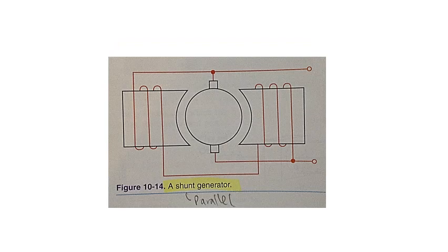The self-excited generator. A self-excited generator uses no separate source of voltage to excite the generator field winding. The self-excited generator produces a small voltage when the armature windings cut across a weak magnetic field. This weak magnetic field is caused by magnetism left over in the pole shoes or field coil cores after the voltage and current have ceased to flow. The magnetism left in a magnet after a magnetizing force has been removed is called residual magnetism. Residual magnetism was first discussed in Chapter 9.